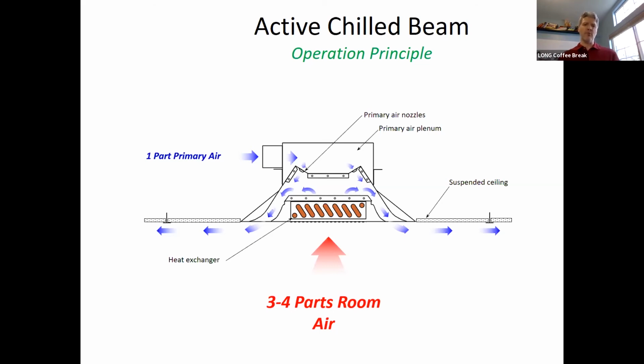Another way that we've done that before is installed cooling only beams, but then upstream of that on the outdoor air coming into, let's say, 3 or 4 beams, whatever you might zone out to be either that room or that zone, you could put a hot water coil within that ductwork. That way you don't have to run hot water coil to each of the beams themselves. And then to further augment that, especially for the outdoor air, we've used things like the air control valves, which we covered about a week or 2 ago, in order to control the air going to that. Because again, the quantity of air going to these needs to be set up during the time of installation and is very important to how that chilled beam itself acts and the loads that it gives.